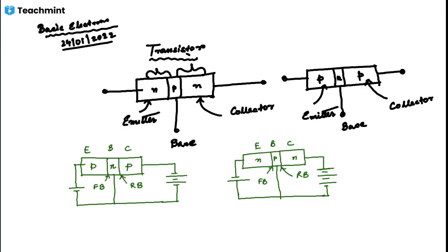In each type of transistor, the following points may be noted. There are two PN junctions, therefore a transistor may be regarded as a combination of diodes connected back to back. They have three terminals, one taken from each type of semiconductor. The middle section is a very thin layer. This is the most important factor for the function of the transistor. Why is it named transistor?